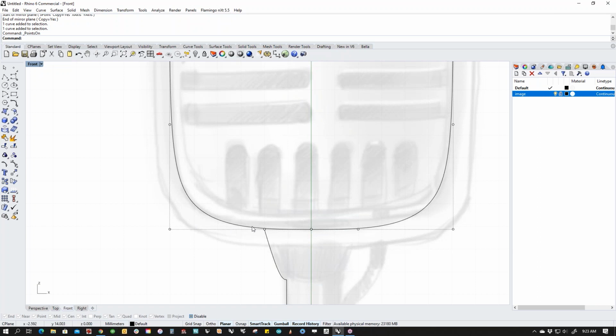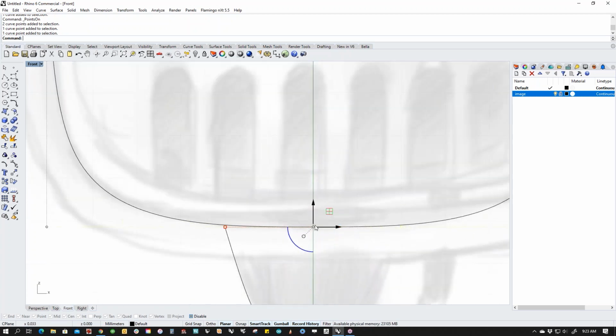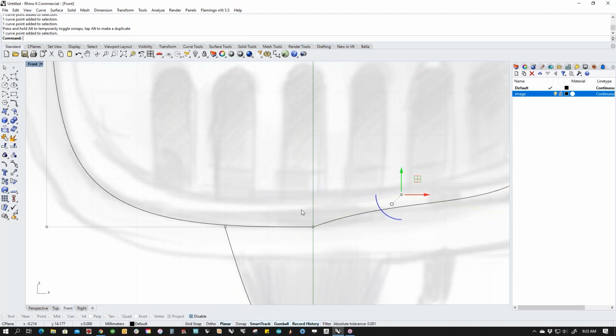And in this case, if I were to grab the 0 point, right, this is the positional tangency point, and then the tangent point, which is the next one out, the G1 point, you can see that gumball reports back with no scale handle in this direction. If they were out of scale, like this, gumball would have a handle down here, but it doesn't. So that means that these are in a straight line, which means we have centerline tangency.